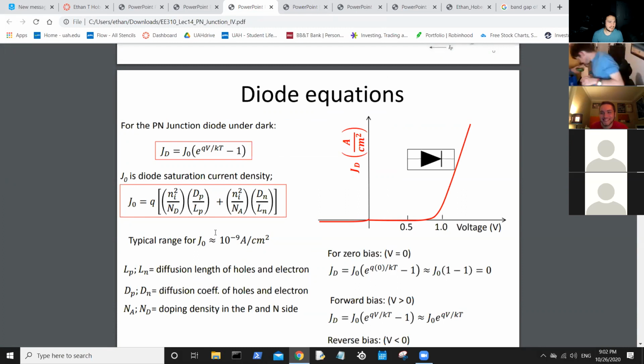All right. Because obviously this is recorded, so we don't need his personal stuff being blasted. So we look at this formula. We know what DP will be given, and we know what Ln is. So the minority carrier lifetimes are going to end up in the denominators of those second terms across the sum. So your LP and your Ln are going to include two separate minority carrier lifetime values. They'll probably be the same, assuming this is a symmetric PN junction. Otherwise, they wouldn't be, because you'd have to calculate each of them separately.